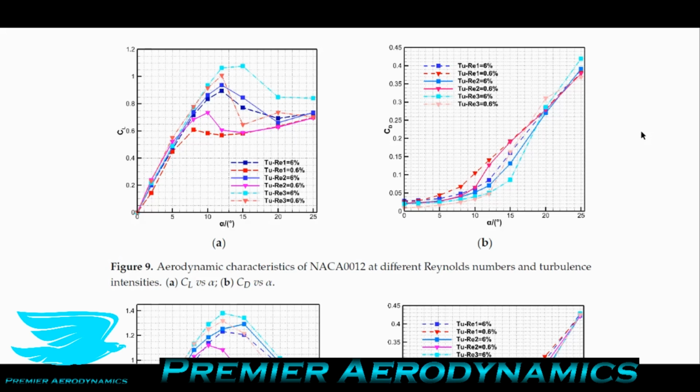So again, if you want to learn more in depth about how an LSB forms and what it is, check out podcast number 11. However, I'm just going to cover it here quickly. What a laminar separation bubble is: the flow is first of all laminar to begin with. Then it gets to a point where it's starting to become a little bit transitional and it will detach from the surface. And then it will transition as it's detached from the surface, and then it'll reattach. And when it reattaches, it's already turbulent. And in that reattachment zone is this recirculation zone. And it's very slow moving flow in here. That's an LSB, a laminar separation bubble.